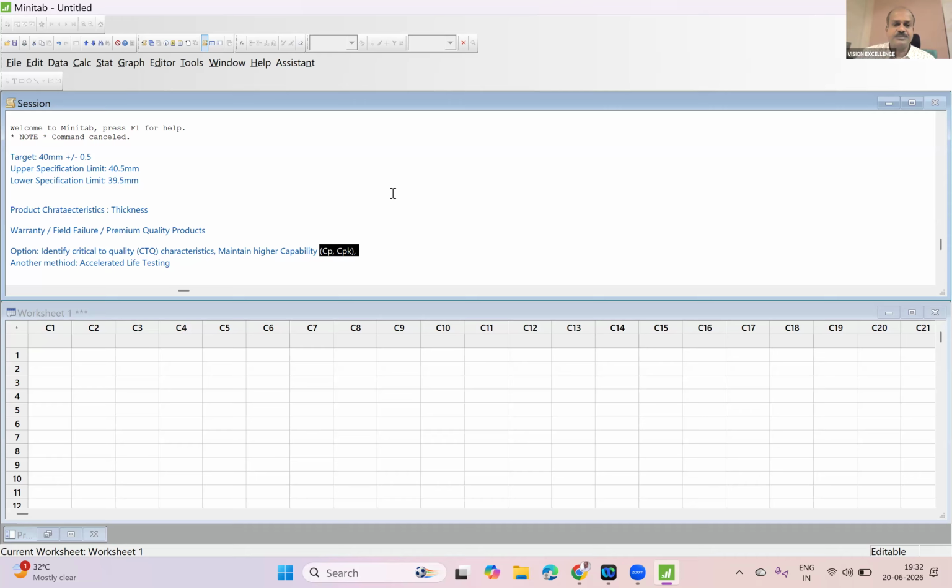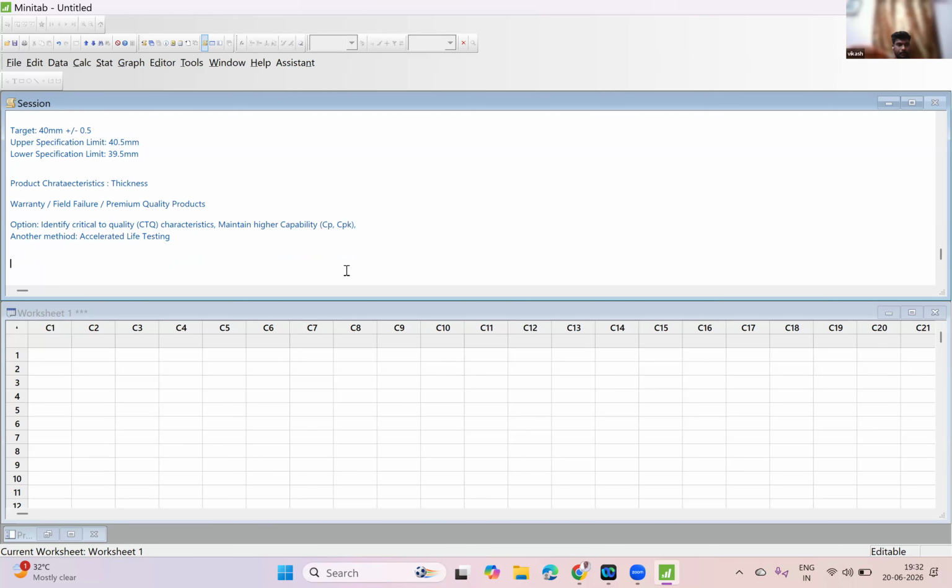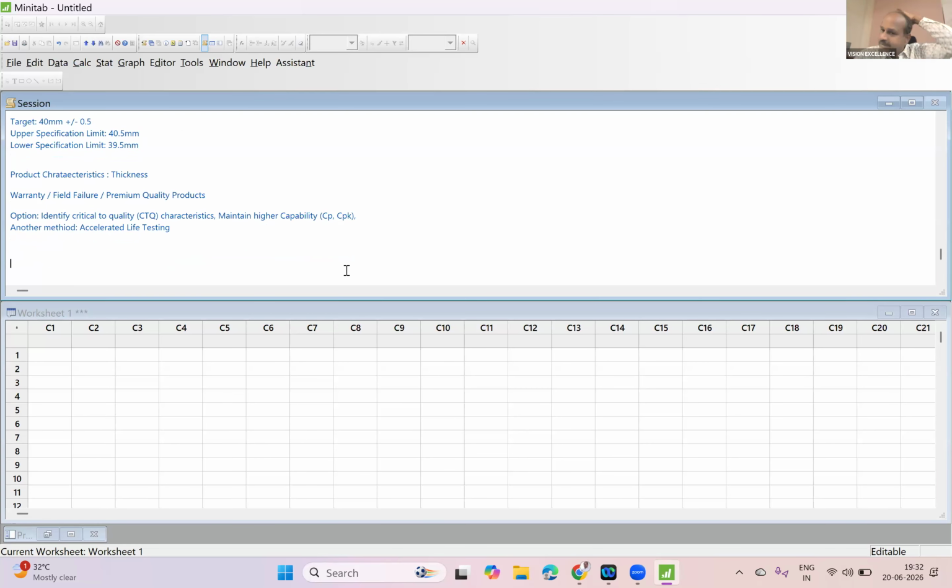Are you getting my point, all of you? Yes, sir. Okay, so the CP/CPK study should be part of your initial quality planning, and thereby quality is assured to your customer. And another option, if you do not have CP/CPK in place but still want to ensure the field life and everything is in place, then you have to focus on accelerated life testing. If accelerated life testing gives you a poor life, then probably you have to come back and focus on all critical parameters only.